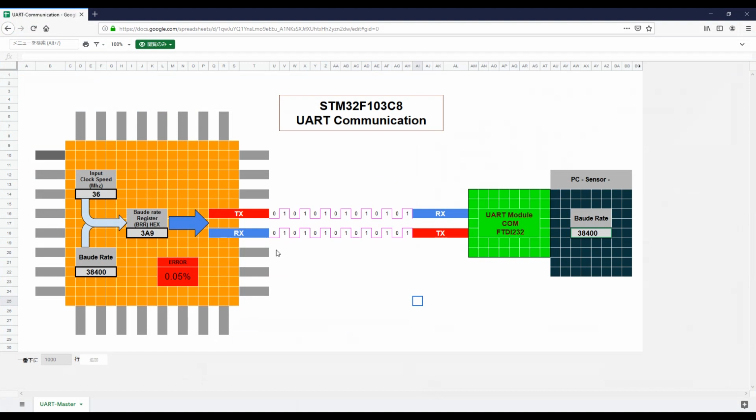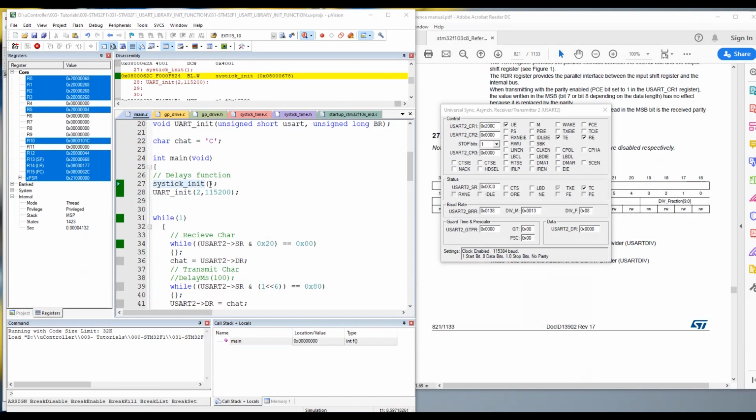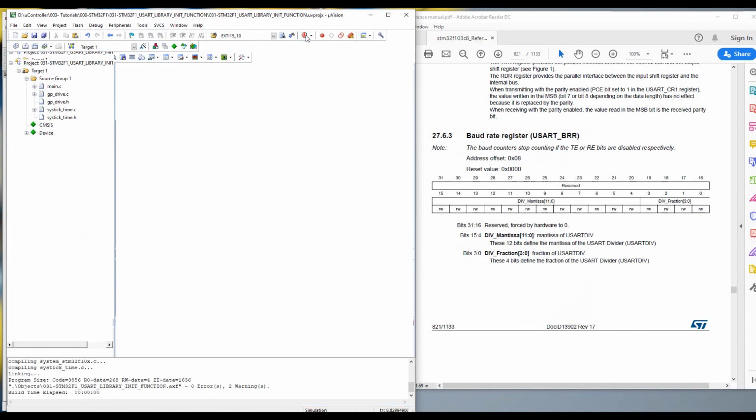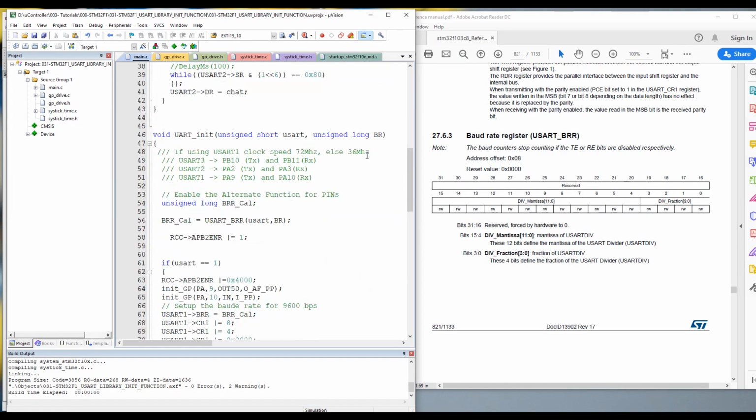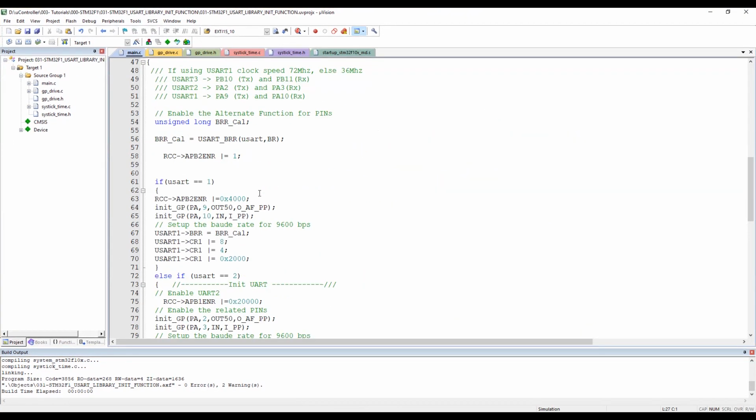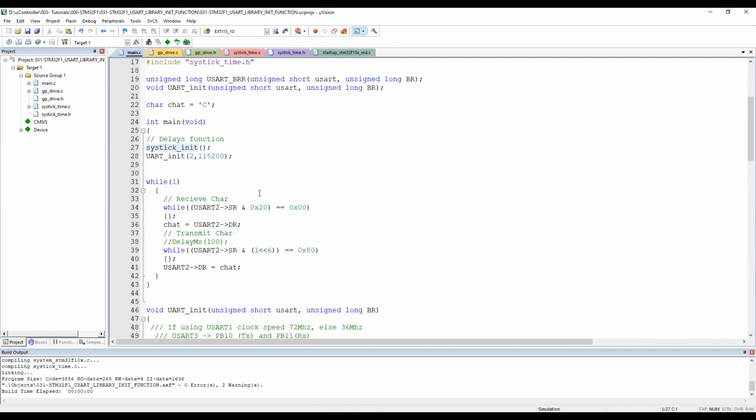As we have only 4 bits to input the digit for the baud rate division, there is a small error happening each time. And if I put here again the 11,000, we do have a 16% error happening. So that should be normal, but let's make a real test. Okay, so we still have the same code for the send and receive, this one.